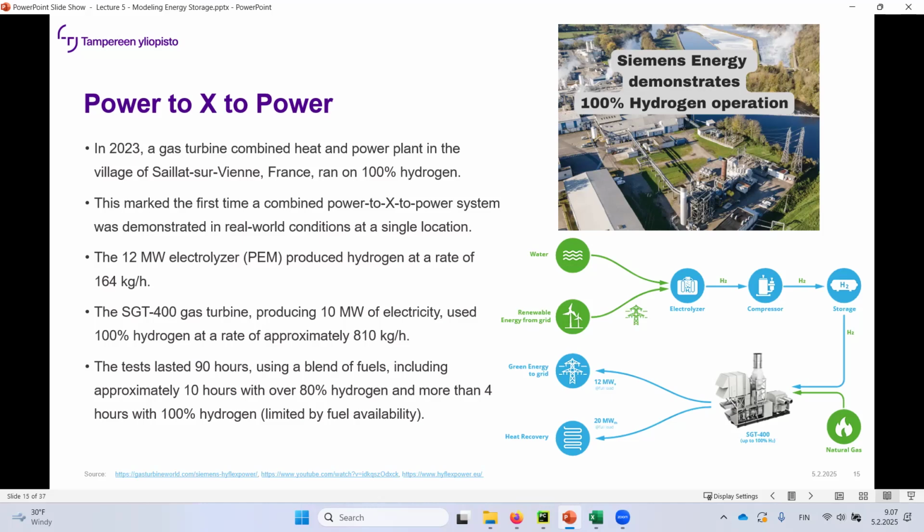But the main restriction in here, contrary to the common belief that the electrolyzer can follow the load and the electricity price, so you can switch it on and switch it off and switch it on and switch it off, that doesn't really apply. The electrolyzers at the moment are still so valuable, they have so much capex that you have to produce the hydrogen pretty much year round. So you cannot really follow the electricity price that much.